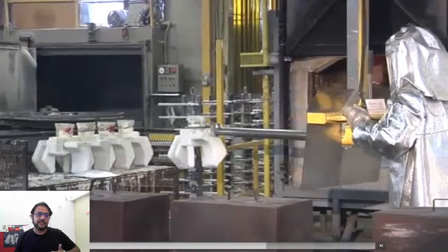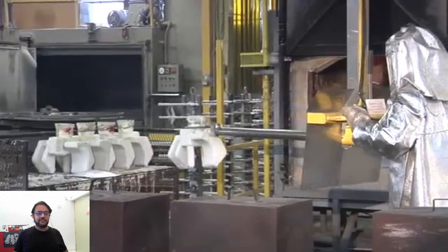So now think about what has happened. Once you have this kind of mold, the wax is inside, right? Naturally no metal can go in. Till now the cavity hasn't been formed, so you put it in an oven and heat it up, and the wax either evaporates away, or you can melt it away and remove it from the whole ceramic piece. Now internally there is a cavity created. Wherever there was wax, there is no longer any wax.